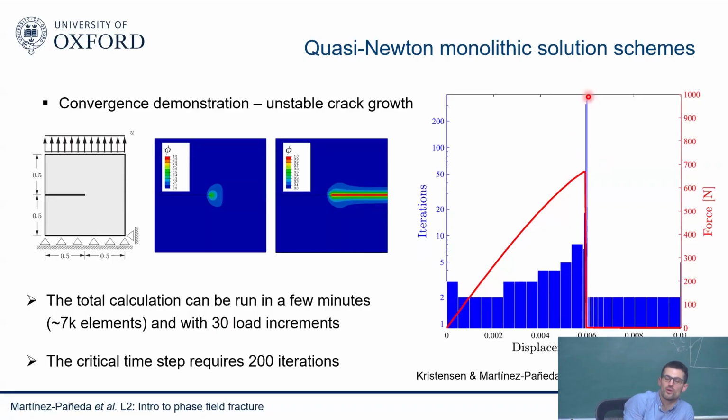And that's something very peculiar of phase field. Because normally, and in fact you need to tell Abaqus, with Newton methods, if you don't get convergence in 5 or 10 iterations, then you lose all hope. Newton-Raphson is not going to find the solution. So normally Abaqus will stop looking for solutions at 5. It will just start decreasing the load increment and doing other things. So you actually need to tell Abaqus, hey, give it a bit more time, because it may find the solution.